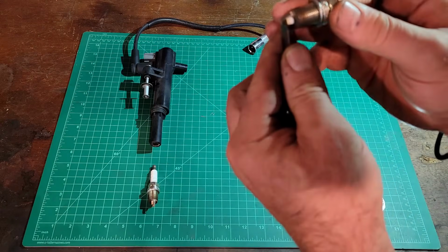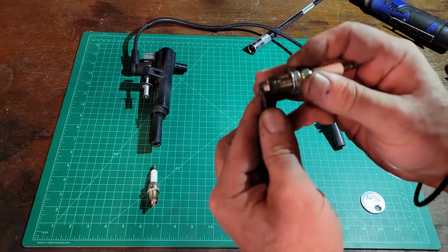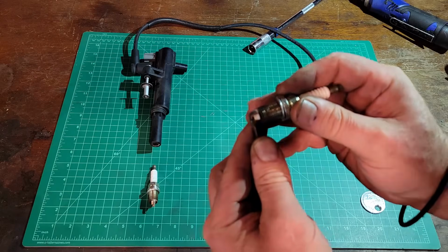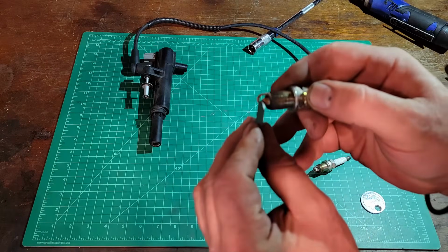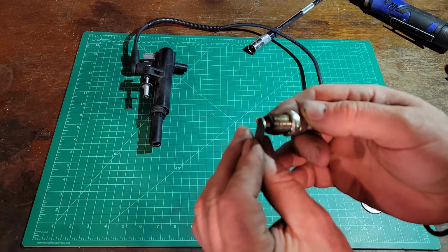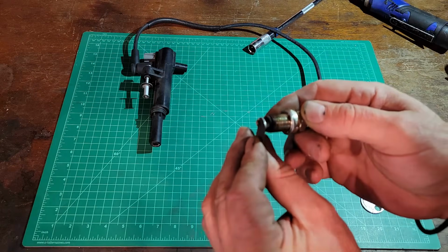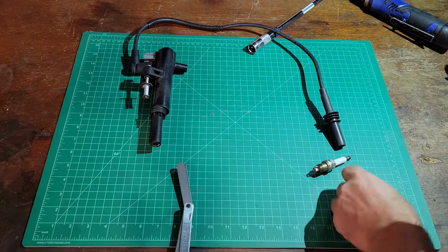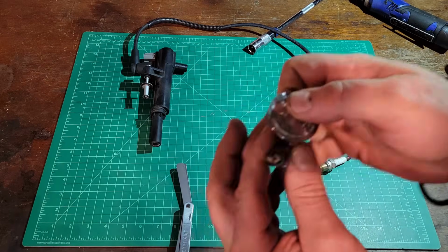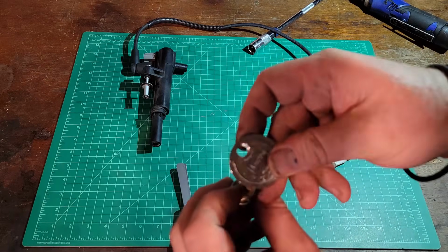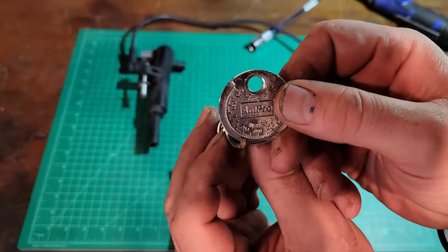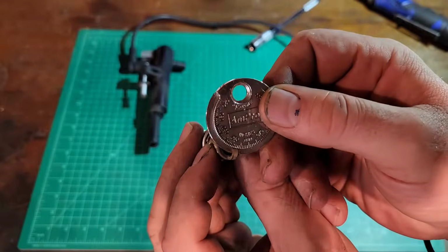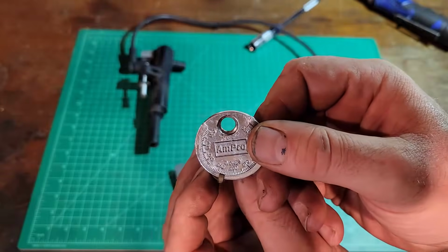Like you could see the gap on this one. I can't even fit the gauges in. The gap on this one has room for plenty more. So that's when I just use the little gauge, the little disc. Now I don't like these for setting, but you could tell we're about 53 thousandths.